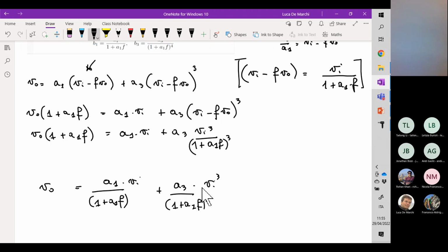So the Nyquist criterion states that the system is unstable if the transfer function related to the multiplication of A(s) and F(s), which is also called the loop gain, has an amplitude larger than unity at the frequency where the phase of the same quantity is minus 180 degrees.